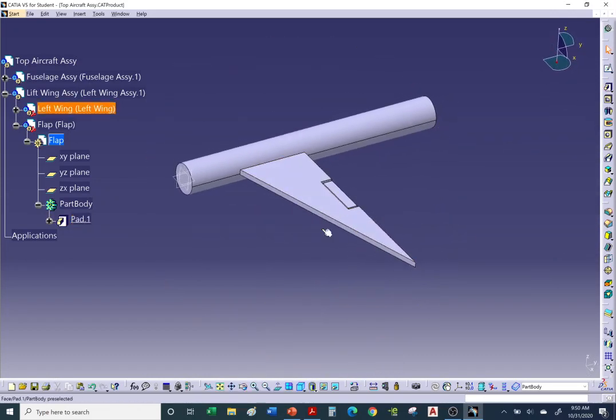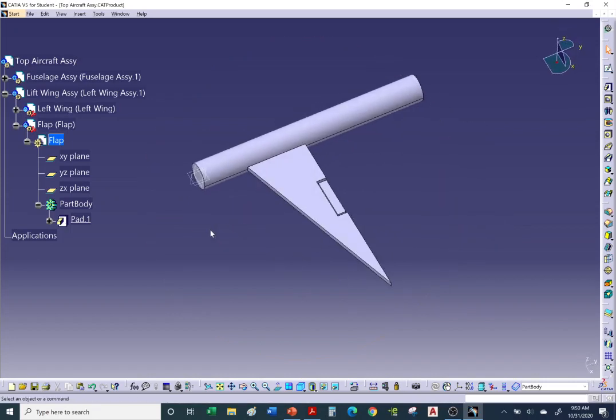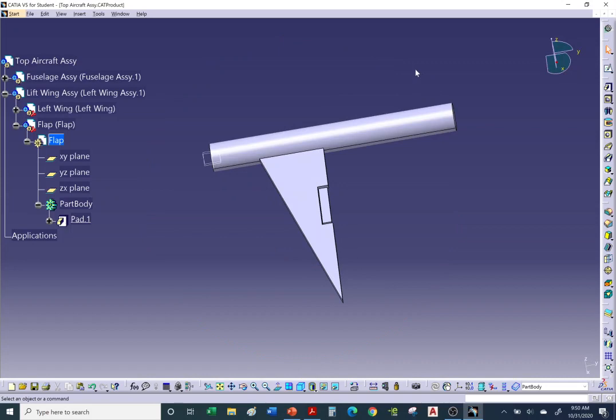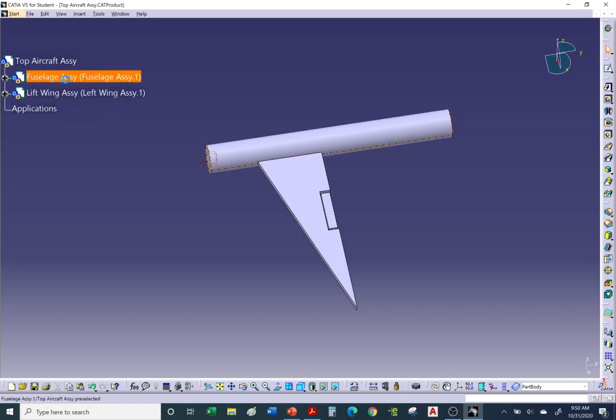Okay, so this is referred to as top-down. Just wanted to give you a little taste for what is top-down modeling. Okay, so then we would insert a new binder. So currently I have the fuselage binder, the left wing. I would then do a right wing assembly. Okay, so the right wing and left wing are first assembled separately, then they're attached to the fuselage.